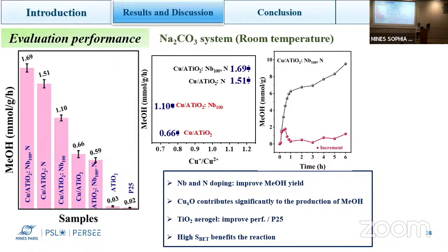So I liked very much the evolution regarding this impregnation process. At the beginning, you impregnate. There is still this problem of intrusion of water inside the porosity, but okay, you impregnate and then you dry in the oven and you make some xerogels. And finally, the specific area is something like 1 or 2 square meters per gram. So it is okay, peanuts, nothing. Then you said, okay, this is not a very good way to work. I'm going to use supercritical drying. And this supercritical drying finally didn't work very well because of the elution of the particles during the solvent exchange, the water, which is not miscible with CO2.